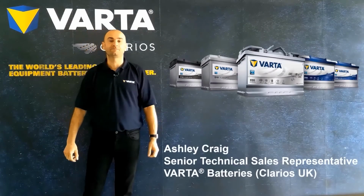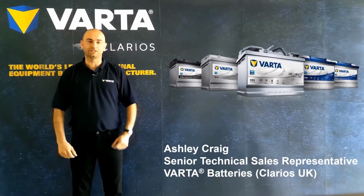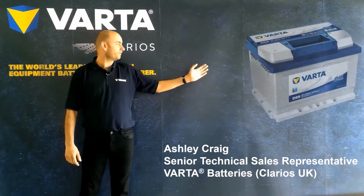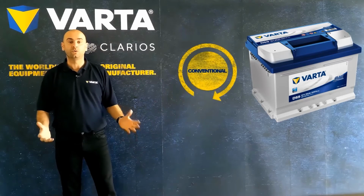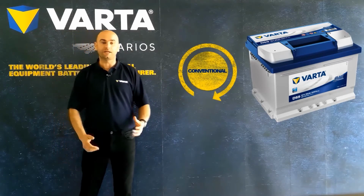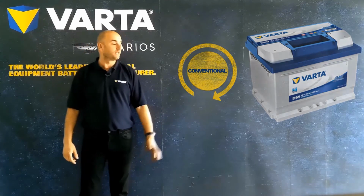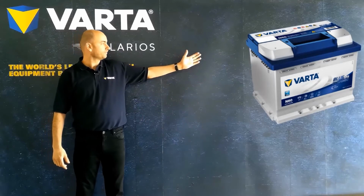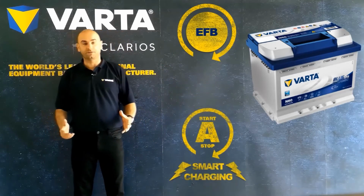There are various types of battery technology used on vehicles, depending on the vehicle age and technology demands. Here we have an SLI, starter, lights, ignition, or conventional wet lead-acid battery for vehicles up to 2000. The job of the battery is to start the engine and power a limited amount of consumers. Here's the EFB, Enhanced Flooded Battery. It's the entry-level start-stop battery.